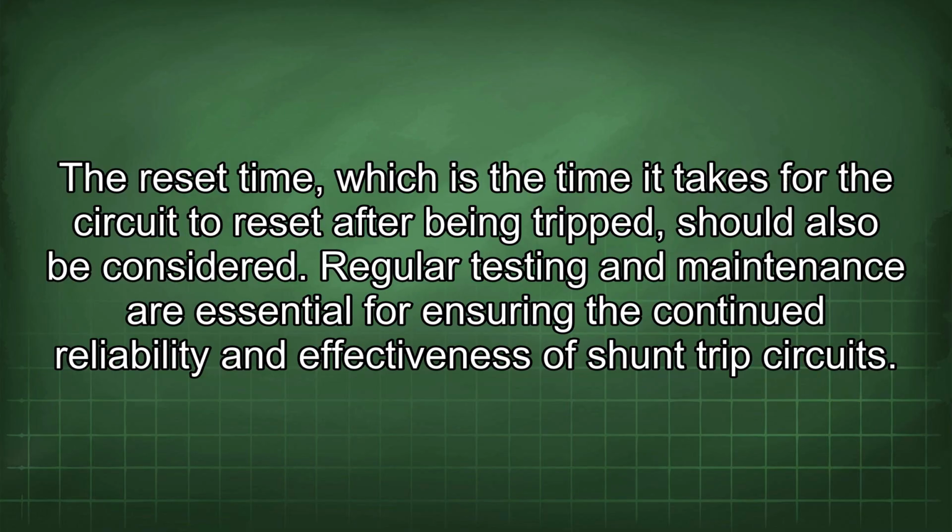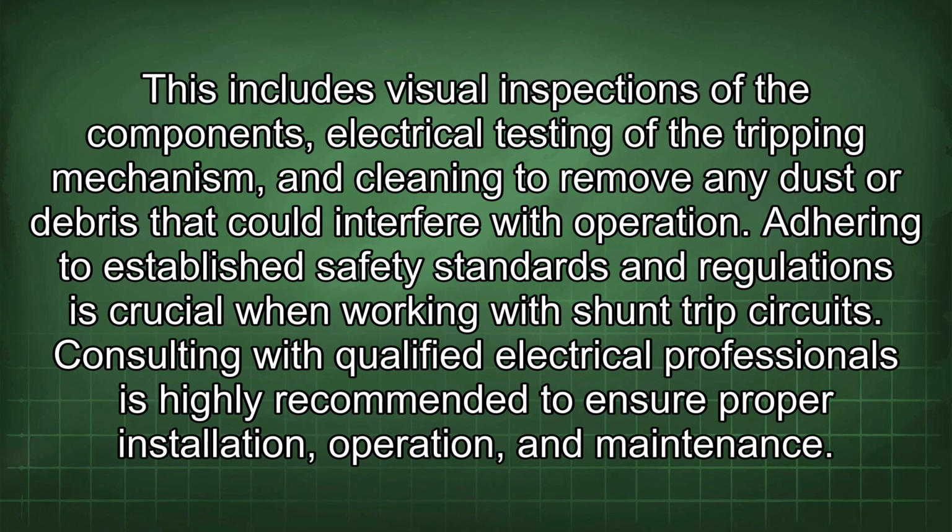Regular testing and maintenance are essential for ensuring the continued reliability and effectiveness of shunt trip circuits. This includes visual inspections of the components, electrical testing of the tripping mechanism, and cleaning to remove any dust or debris that could interfere with operation. Adhering to established safety standards and regulations is crucial when working with shunt trip circuits. Consulting with qualified electrical professionals is highly recommended to ensure proper installation, operation, and maintenance.